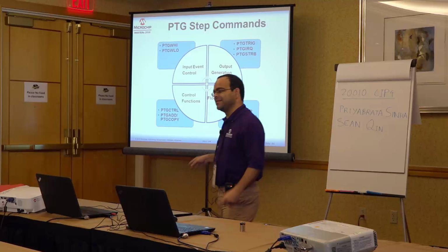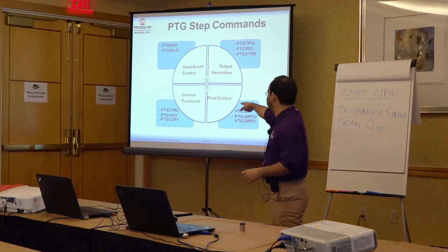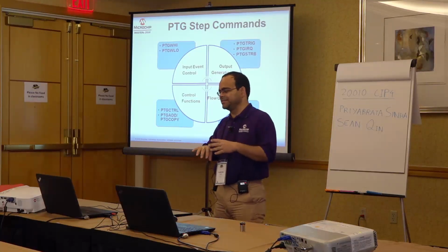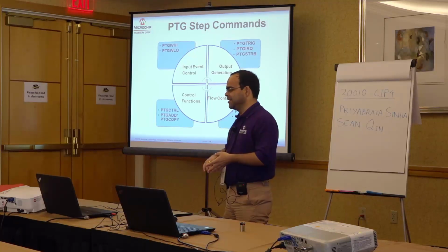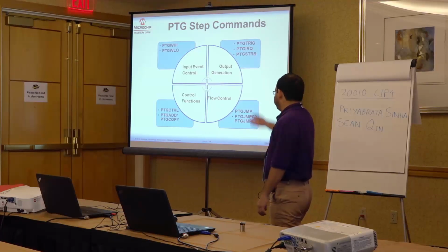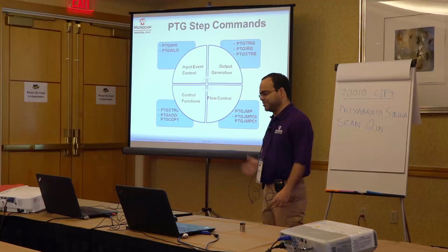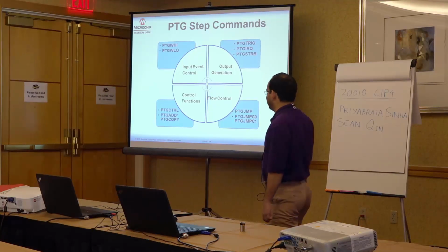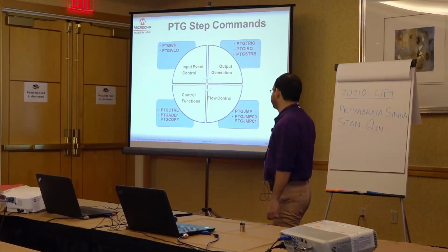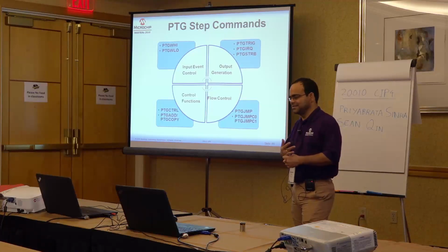So here it is updating a register that is not internal to the PTG, whereas this PTG add or PTG copy commands update registers that are internal to the PTG, like the PTG timer values, the PTG counter values, and so on. So there are various control functions, like some of those include enabling the PTG watchdog timer and so on, or enabling software input trigger. Then finally there are flow control commands, which is conditional or unconditional branches.